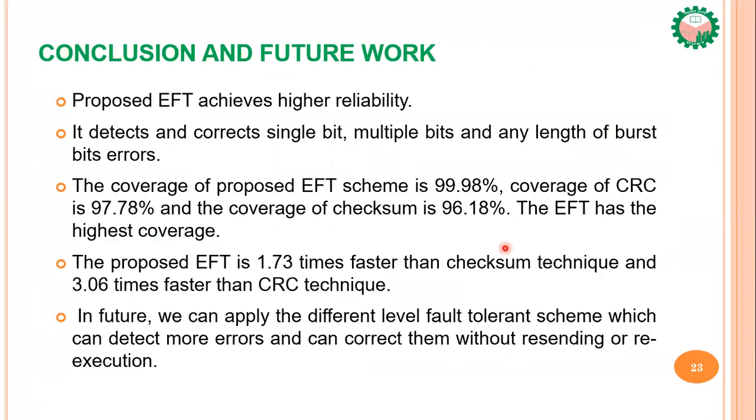The conclusion and future work. The proposed EFT has high reliability. It detects and corrects single bit, multiple bits, and any length of burst bit errors. The coverage of the proposed EFT scheme is 99.98%. The coverage of CRC is 97.78%, and the coverage of CHECKSUM is 96.18%. The EFT has the highest coverage.